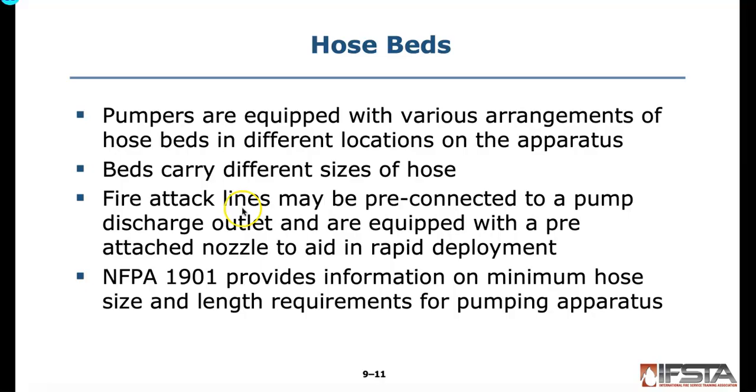There are going to be several different sizes of hose and different configurations. So we use a 3-inch supply line. There are 4-inch supply lines and 5-inch. Those are the hoses that hook up to the hydrant, and you get water from the hydrant into the engine, into the tank. They hook up to the hydrant, they hook up to an intake, and then water flows from the hydrant in by releasing a valve that allows the water to flow into the tank.